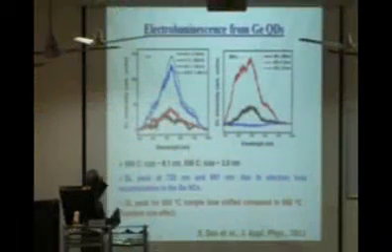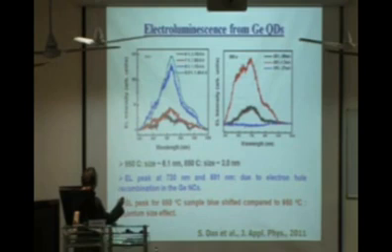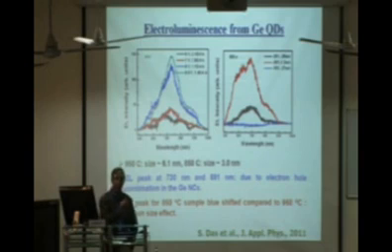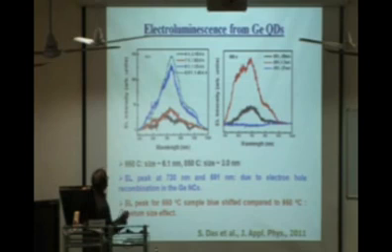And of course we get a very nice emission. In this case I am showing two different samples. This is a better sample. Typically you start getting emission at up to 6 volt, and as you start increasing the bias voltage, the emission intensity or electroluminescence intensity goes up. So here you don't have to excite the quantum dot with a laser. This is an electrically operable so-called device. And forget about this, this is a different sample with a little bit more defects.